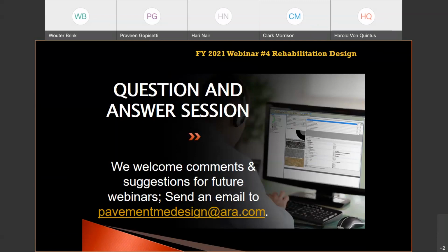Good question. The answer to that is it is not a requirement. BCT is not a requirement for Pavement ME. Some agencies do use deflection testing as their standard practice. Obviously, not all agencies do. So you can use rehab input level 2, and that's using the distress surveys.